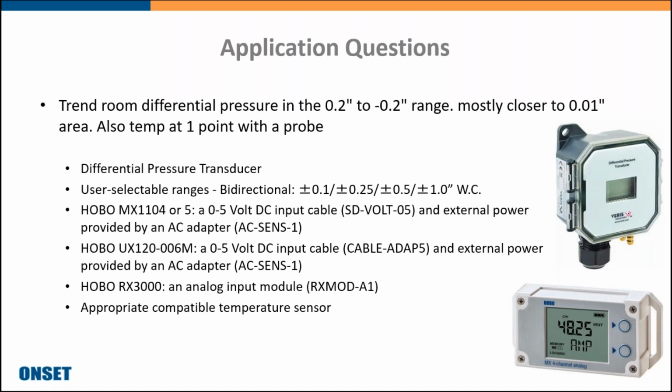When using our RX units indoors, you can connect them to AC power to keep that internal battery trickle charged. Then if there is ever a power failure at your facility, the data logger will continue to record on that battery backup power. And again, for the temperature reading here, you can just connect any compatible temperature sensor to any of the data loggers or remote monitoring stations I had previously mentioned.